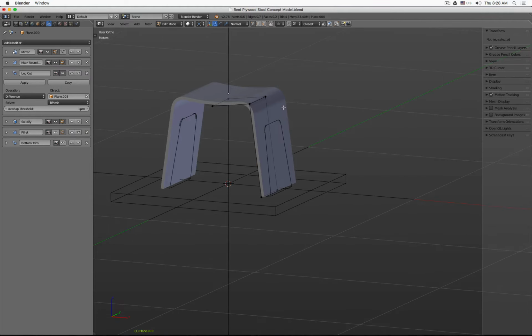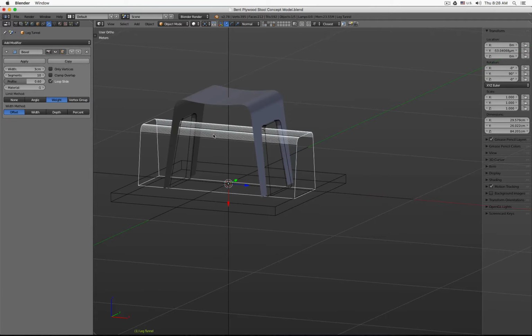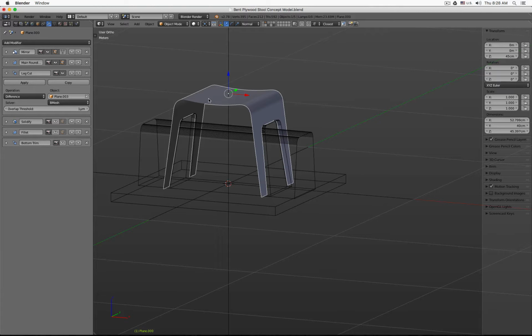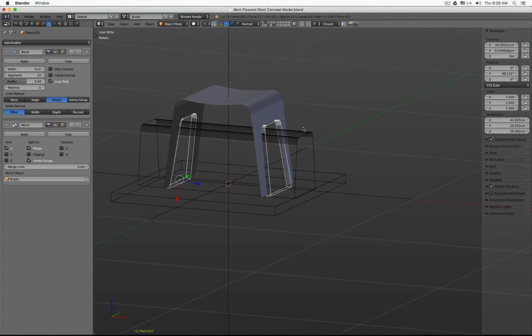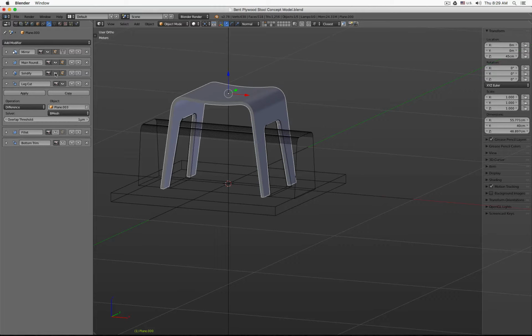Because traditionally Blender, or polygons in general, can have an issue, as you saw, with opening this out of a flat surface. It is easier, when we do volume manipulations, to just in general work with volumes, to cut out of not a flat surface, but for example better a volume itself. And then it honestly doesn't really matter how we cut it.